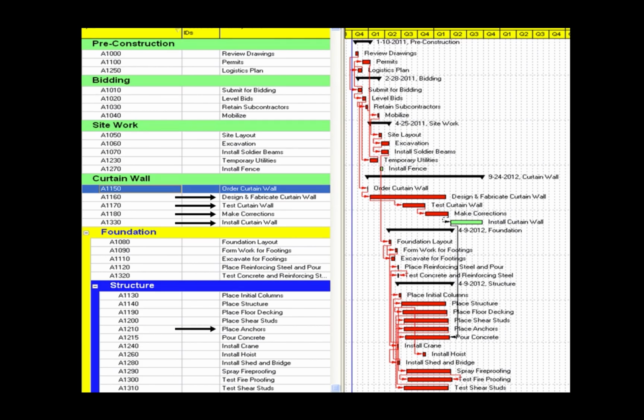It's usually on the onus of the contractor to develop those working drawings, because they're usually a combination of a lot of trades or a lot of elements. So your steel fabricator is not going to do it for you. The concrete firm that you hired to do all your concrete work is not going to do it for you. But you as the general contractor, or owner, will have to have proper working drawings.